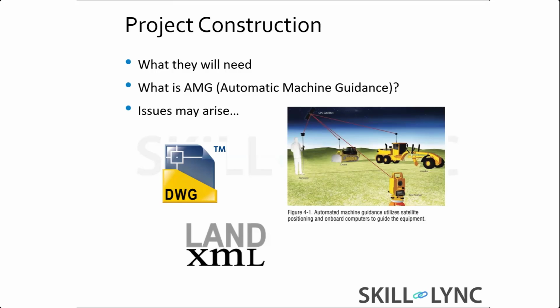They may also ask for LandXML from you. LandXML is a non-proprietary format, and it's a way to export your model. It's almost like a text file, but all civil engineering software out there, including the software in the graders, can read LandXML. And that LandXML file is then used as the model, okay?